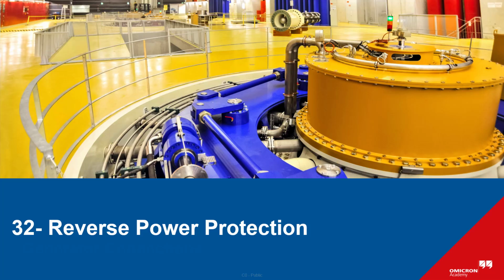In this video we will discuss the reverse power protection function 32. This protection plays a key role in turbine-driven generators, especially steam turbines, to prevent mechanical damage or overheating during shutdowns. We will explore how the reverse power relay detects motoring conditions, why it's critical to trip the generator breakers, and how the settings are chosen based on the turbine type and operating characteristics.